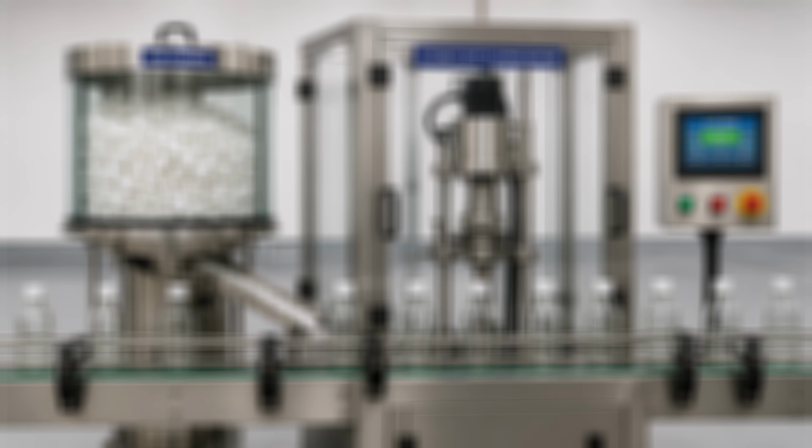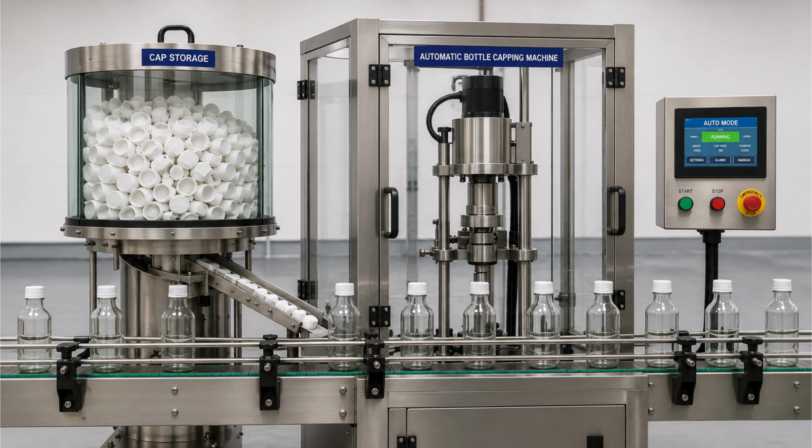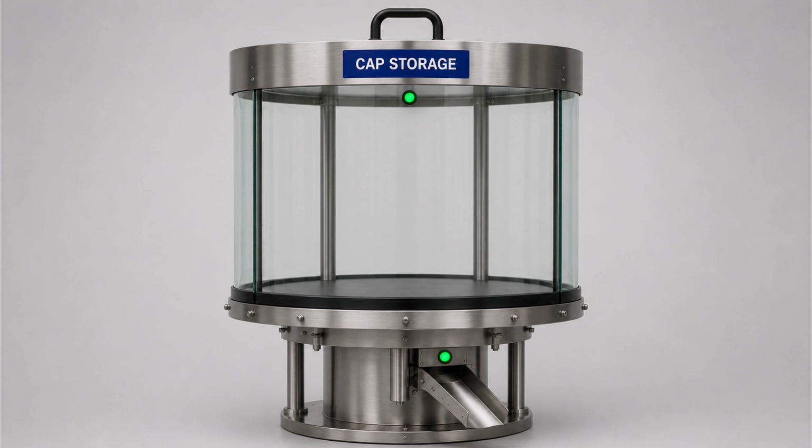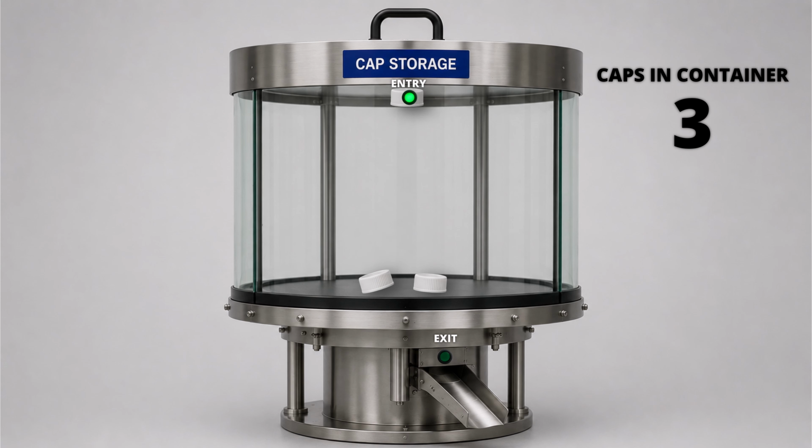So to explain the less than or equal to instruction, the example goes like this: there is one bottle capping machine which has a container that stores the caps of the bottle, and we need to monitor the number of caps remaining in the container. For that, there are two sensors placed at the entry and the exit of the container. Whenever a cap enters the container, the sensor will detect that cap and our counter will increment by 1, and every time a cap goes out of the container, the sensor down here will send a signal to our counter, which will decrement the count by 1.